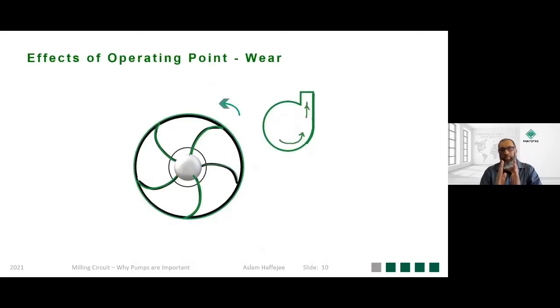Coming to where we should be with our wear, you'll notice this is operating close to BEP or preferably on BEP. And the thing here is, you'll notice that the flow and the vanes match. They match very closely. So what will happen here is you'll get very even wear. Right? Remember, your impeller is going to wear sooner or later. But the important thing is you are aligning your wear with the vane and the shape of the impeller, and therefore it will wear much more evenly and provide a better wear life, a longer wear life.